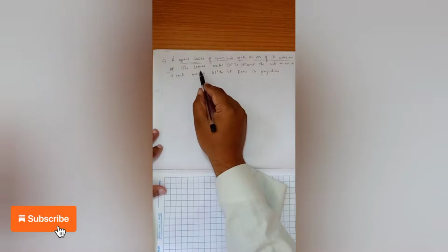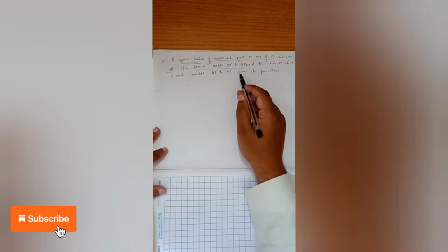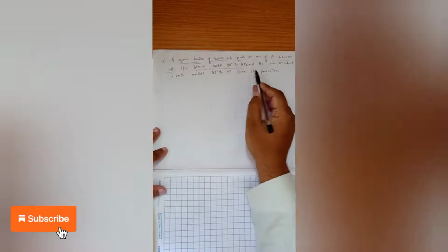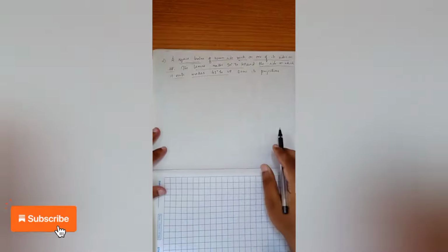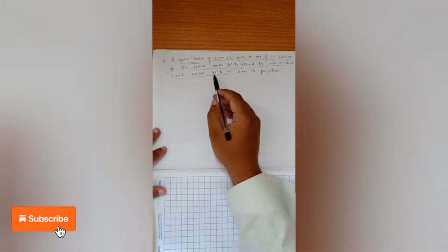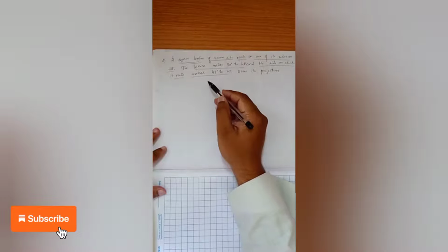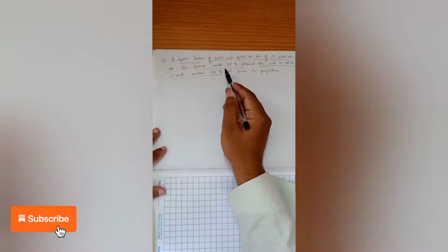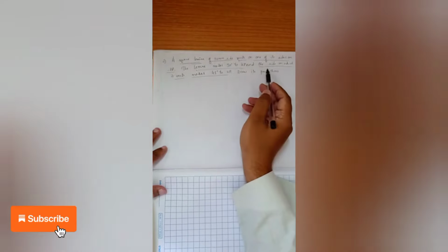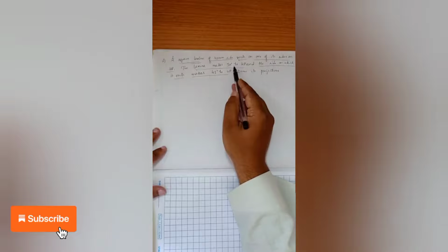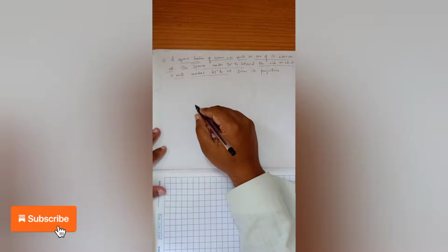Okay, now the lamina makes 30° to HP, that is the inclination of the lamina, and the side on which it rests makes an angle of 45° to VP. From this question we can understand that both inclinations are with respect to the edge or the side. The lamina makes 30° to HP means it is inclined with respect to the edge, and then the same edge which has been inclined to the HP makes an inclination to the VP. So it is a normal type problem.